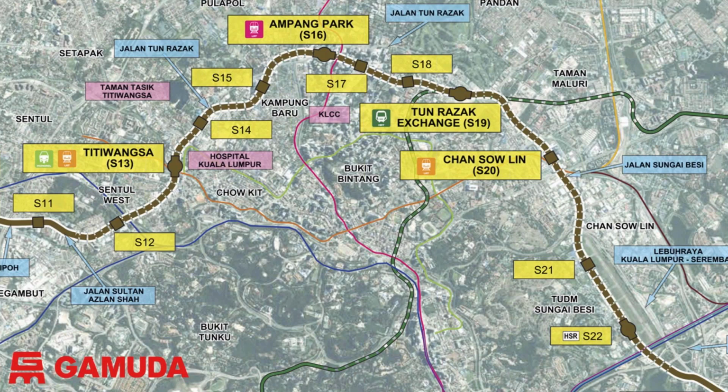It's a design and construct contract led by the MMC Gamuda contractor, with AECOM as the lead consultant, with a multitude of other consultants in support. It involves the construction of 13 kilometers of twin bore TBM-driven tunnels through the city, which is a mixture of Kenny Hills soil, which is a compact soil, and karst limestone, which is a treacherous ground condition to mine in.